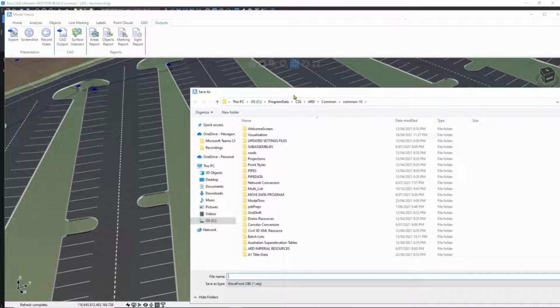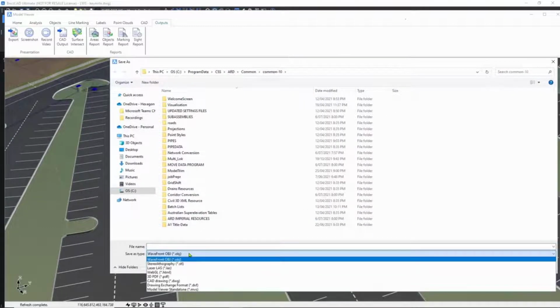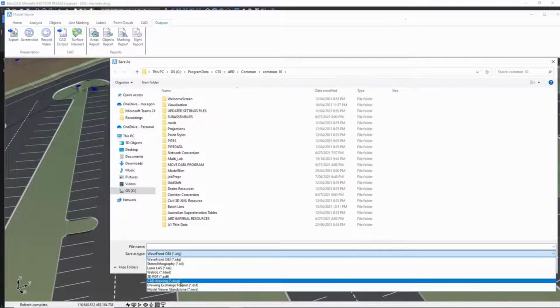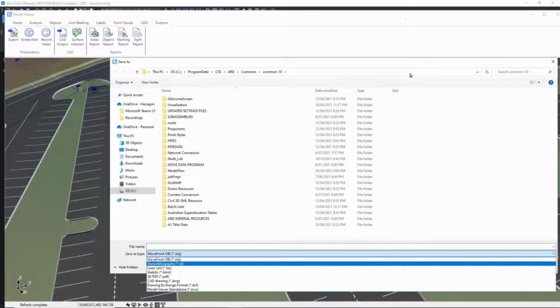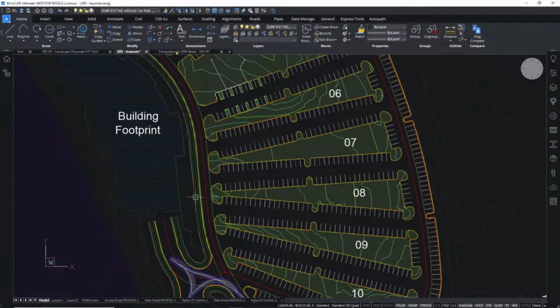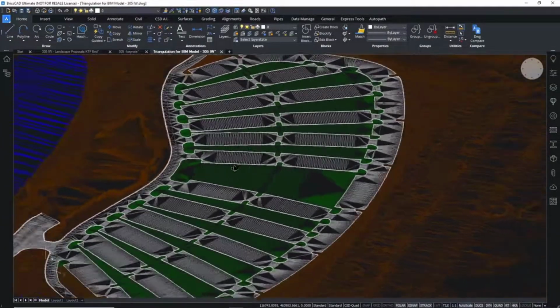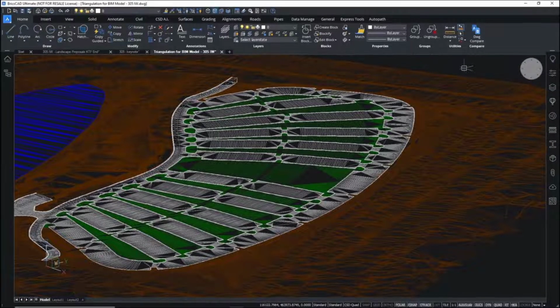In here we've got a bunch of export file formats, from OBJ, to 3D PDFs, and also we can make a DWG texture triangulation file, which we will show quickly here. We'll actually use the OBJ file to import into Twinmotion, but the benefit of looking at the DWG file is that you can do things like match properties and make corrections to any blemishes on the triangulation.